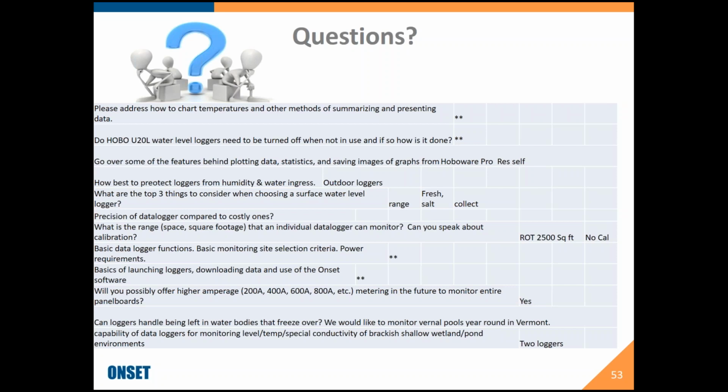Also, the CW series allows you to interface to those sensors very simply with a cable. Almost any third-party sensor, if it has a 4 to 20 milliamp output or a 0 to 24 volt DC output or a pulse output, any of those sensors can be interfaced to our loggers relatively easy. And again, the workhorse of all of that is the UX120-006M.